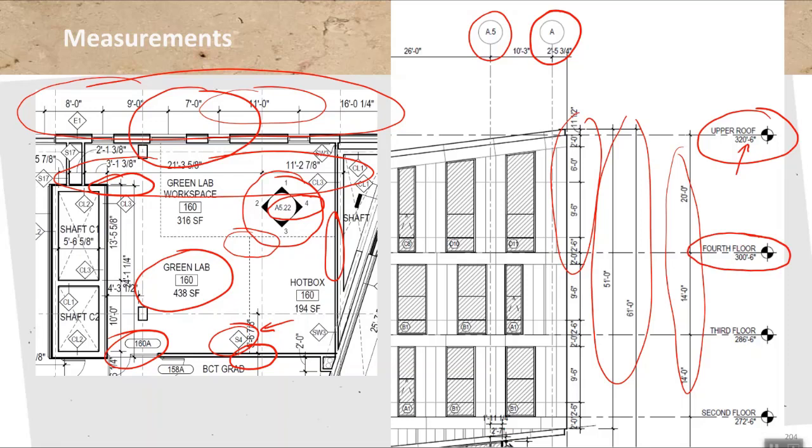One quick word on these elevation tags, or level tags. This is always finished floor height. So depending on what kind of flooring you have, that level is your finished floor height and will remain like that. For example, if you are creating a building in design software and you change the floor type, then of course it doesn't change upward. Usually it changes downward. Okay, so that's the level tags.